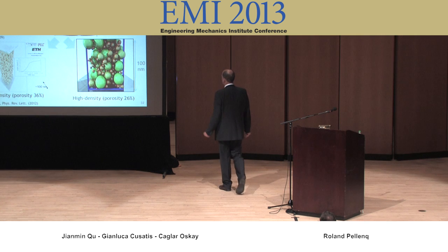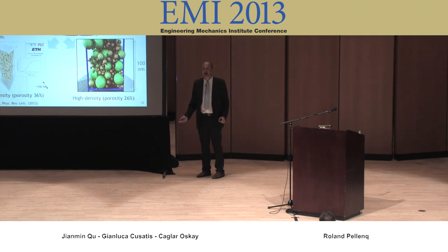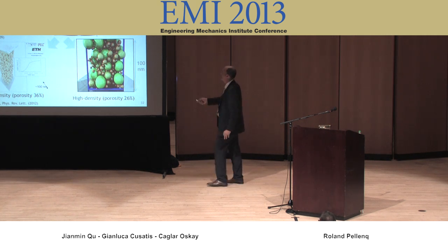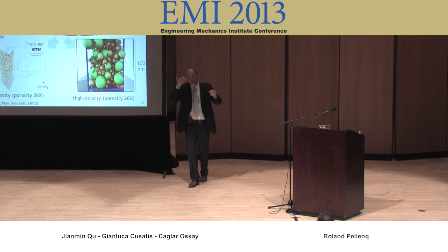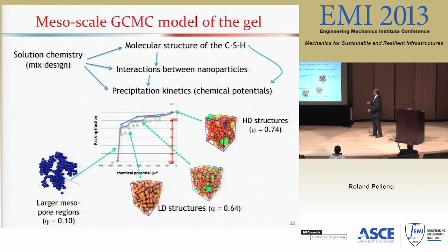But if we want to move to a higher packing fraction or less porosity, ignoring this idea of cubic lattice order, one way is to manage to have a large polydispersity, so that you can pack small grains in between big grains. With this, obviously, you shoot up to larger values of packing fraction. And now my next slide is to tell you about the interaction at some stage, but basically Enrico Masoero, what he did actually is to design a grand canonical